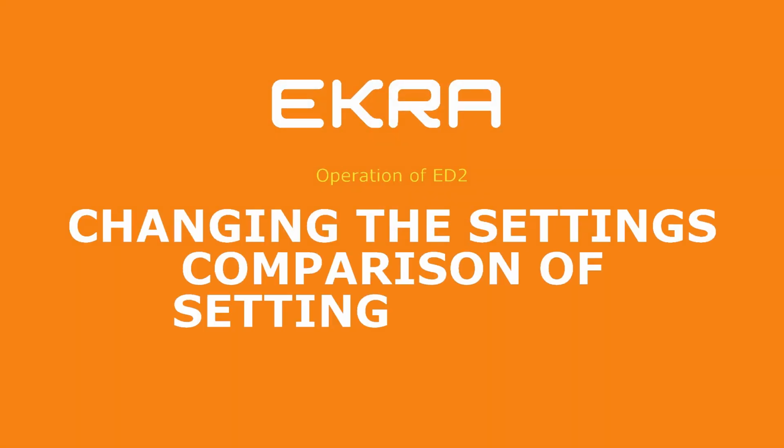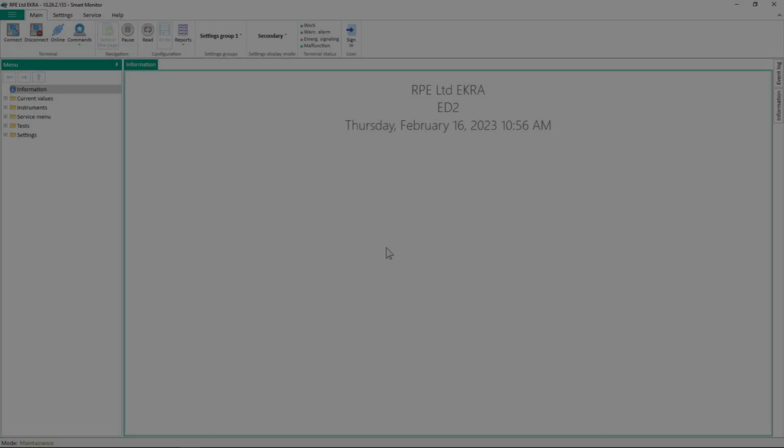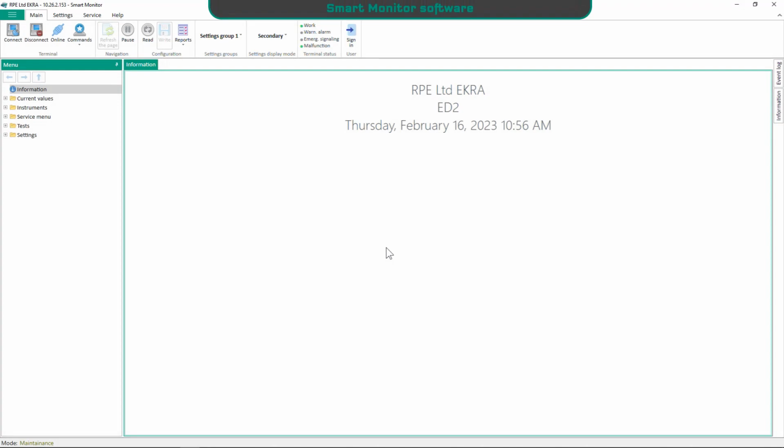In this video tutorial, you will learn how to change settings and parameters of the ED2 series IED via Smart Monitor software and via display on the IED front panel, and also how to compare setting groups. To change IED settings and parameters in Smart Monitor, connect to the IED according to the video tutorial on the operation of ED2 device's IED communication settings with PC.